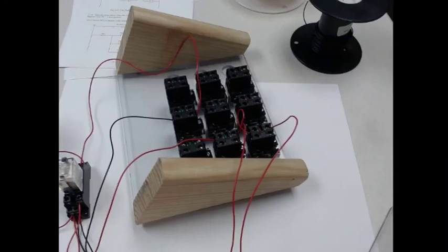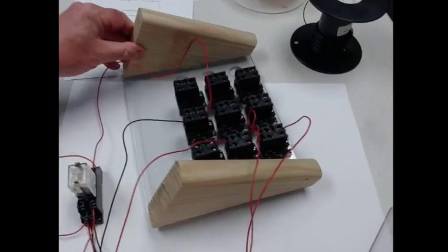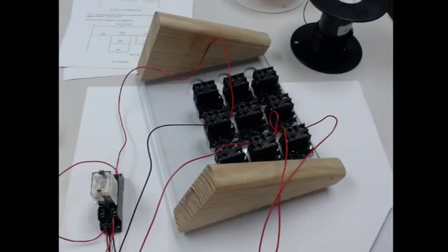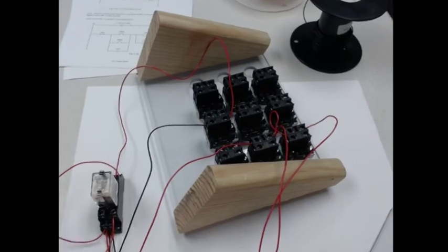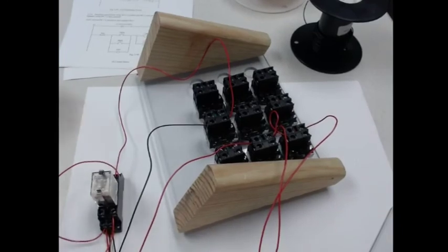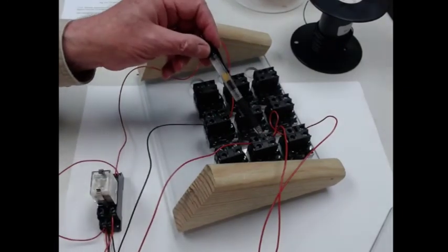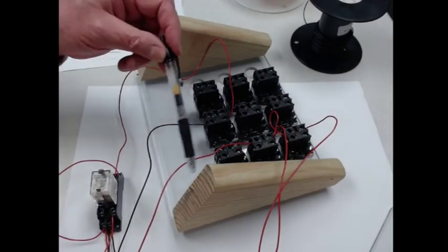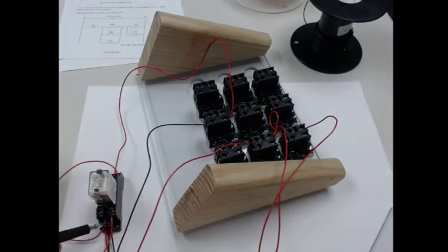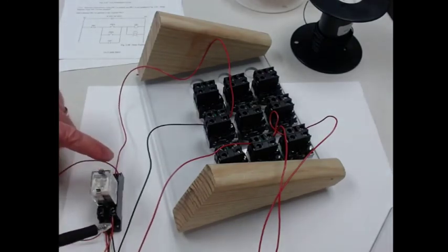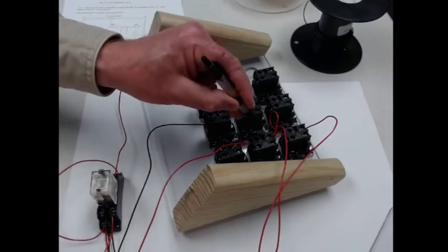So now we are at the end of our story, and we've got the hookup for the page 34 system here. And so we go through the push button, the normally closed push button first, then we go through the normally open push button, then we go from there to the coil. But then we do something kind of interesting. We use a contact off of that coil to feed back to that contact.